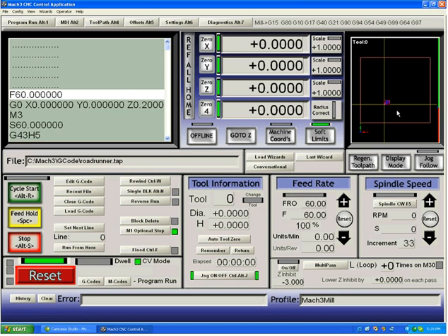You put a piece of material on your mill table, you jog until your tool actually touches your piece of material, you jog your Z down so it touches the material, and then you 0 all of the items. You are then, when you regenerate the tool path, you'll notice my tool path is now further onto my table, and I'm zeroed right at the start point or the origin of that piece.